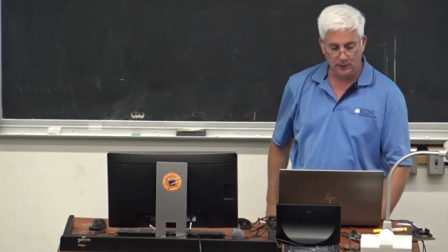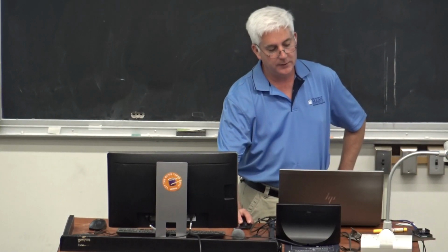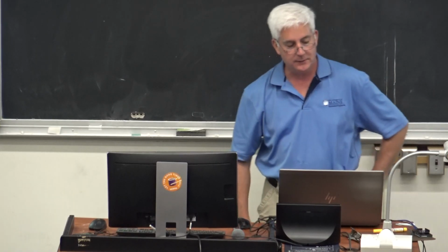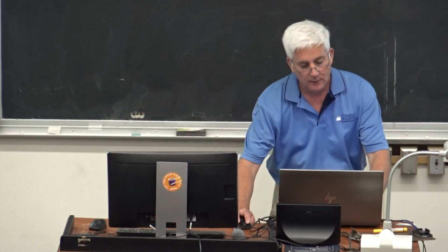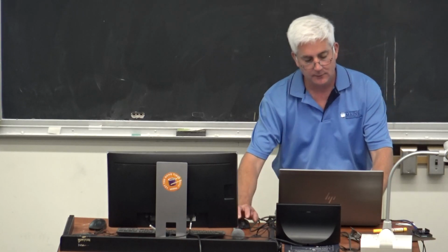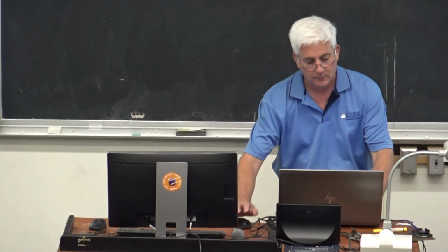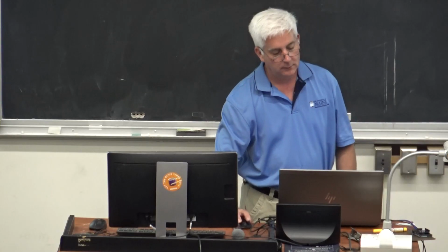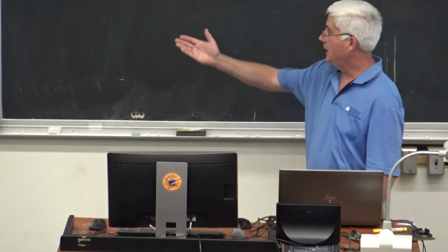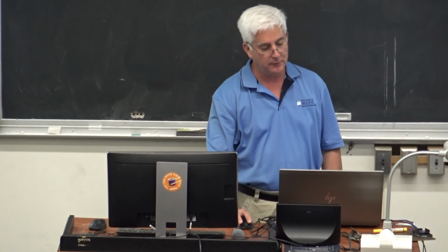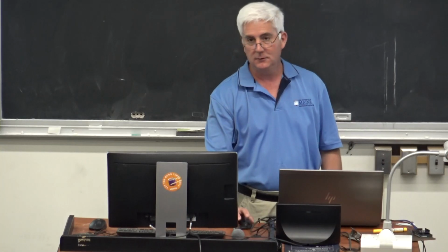Okay, we come down to void loop. So we say digital write. This would be better stated as the actual pin. So this is defined as pin 13. In fact, let me just modify this. That is equally acceptable. So all I'm saying is, I'm going to write to a digital pin, pin 13, make it high.